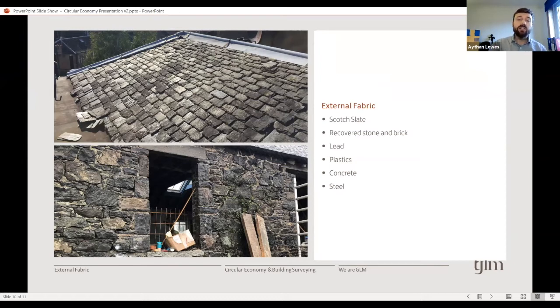Concrete is a huge challenge. It's massively carbon intensive and very hard to separate once cast. Even precast units are grouted in place, making it hard to separate them at demolition. What if we did the same with concrete as has happened with Scotch slates and stopped new concrete manufacture? Do we think we'd be more careful with the existing stock of concrete? Steel holds great promise, but needs braver, more considered structural engineers, as well as connection details designed with recovery in mind.